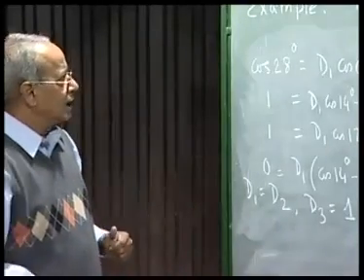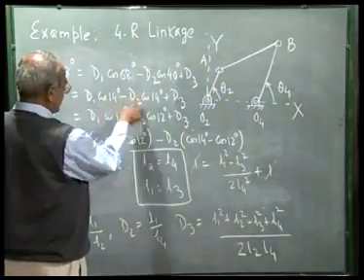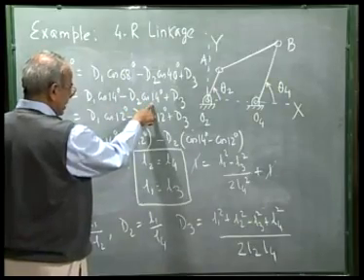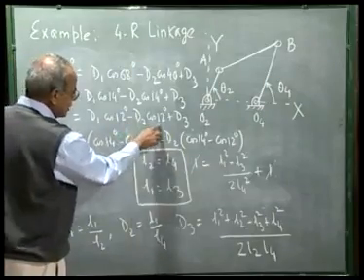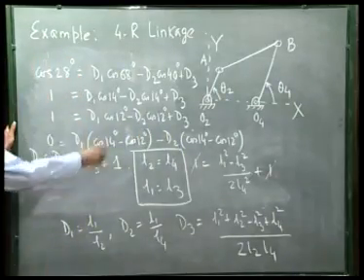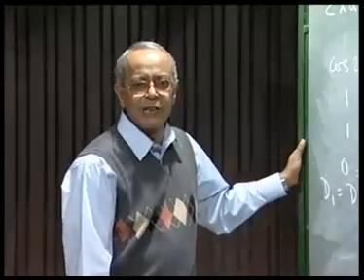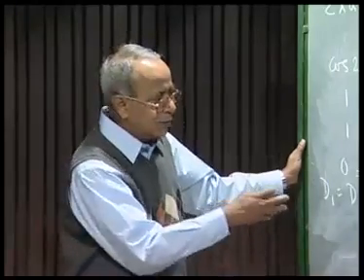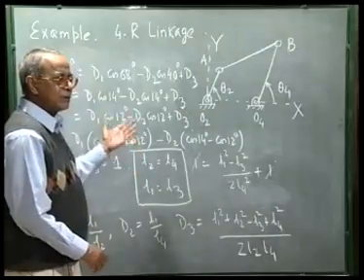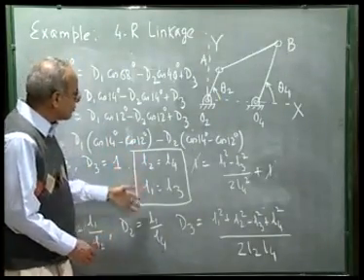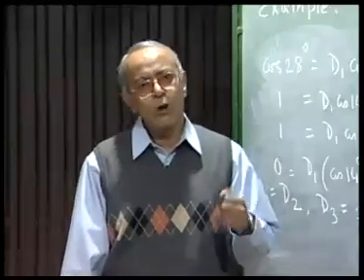It is obvious to note that 14 degree for both theta 2 and theta 4 can be taken up by a parallelogram configuration. Similarly, minus 14 degree plus 12 degree will be also taken up by the parallelogram configuration, whereas minus 68 degree and minus 40 degree cannot be taken up by the parallelogram configuration, and we will see by the model that it will be taken up by the anti-parallelogram configuration, which means we have to go from the parallelogram to the anti-parallelogram branch to obtain all the three configurations. This we will now demonstrate with respect to a model.